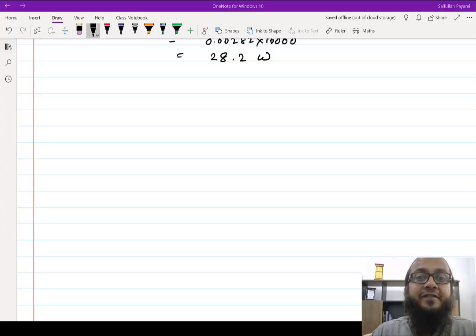So now you have to define the new per unit system. One way of doing it is, from the given per unit quantity, you can compute back the actual quantity and then calculate in the new per unit system. The other way is, there are some expressions based on this same concept, where you can easily compute the per unit values in the new base quantities.